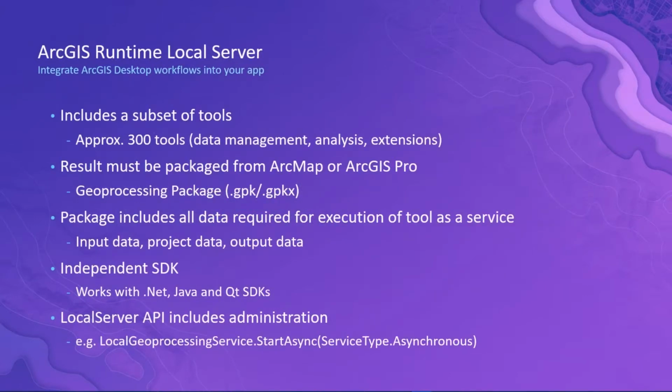So what is the ArcGIS Runtime Local Server? Well, it's the tool that allows you to integrate these ArcGIS Desktop workflows into your own application. It provides a subset of the geoprocessing tools, approximately 300 of the data management, the spatial analysis, and the tools you get with extensions that you can install and run. The result must be packaged from ArcGIS Desktop, so from ArcMap or ArcGIS Pro. That package then also includes all of the data and all of the information that it needs to execute that tool. And it executes it as a local service running on your device.